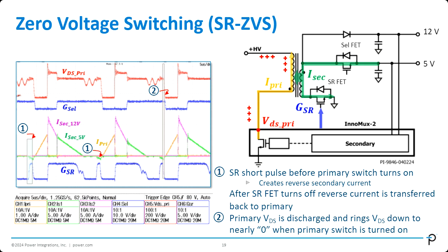As you can see, in order to achieve all of this, we need to have the reverse current on the secondary side. And that means we need to have the secondary discharge current be discontinuous first before we create this reverse current. That means we need to operate in DCM, the discontinuous mode of the power supply. What does that mean to us? Normally designers design power supplies to operate in CCM, continuous mode, at low line input. This is to optimize the RMS current on the primary side. But at high line input, we normally design the power supply to run in DCM.